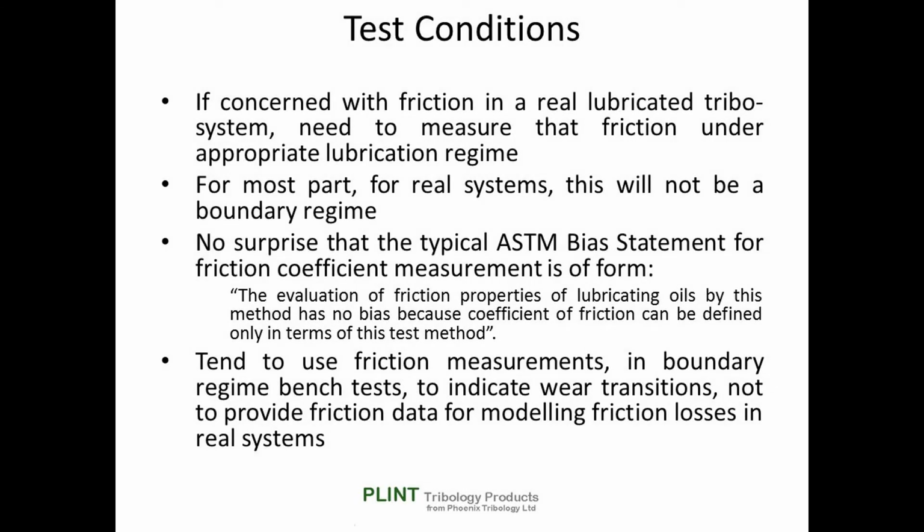It follows that if we are concerned with the friction in a real lubricated tribo system, we need to measure that friction under an appropriate lubrication regime. For the most part, for real systems, this will not be in the boundary regime.